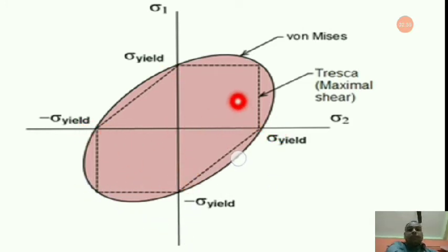So if the stresses developed during working of the metals, whether it is hot working or cold working or forging, whatever it may be, just think of a metal forming process, if your stress is within this graph, say this one or this one, then your material is safe to be hot worked or cold worked or forged or whatever metal forming process.